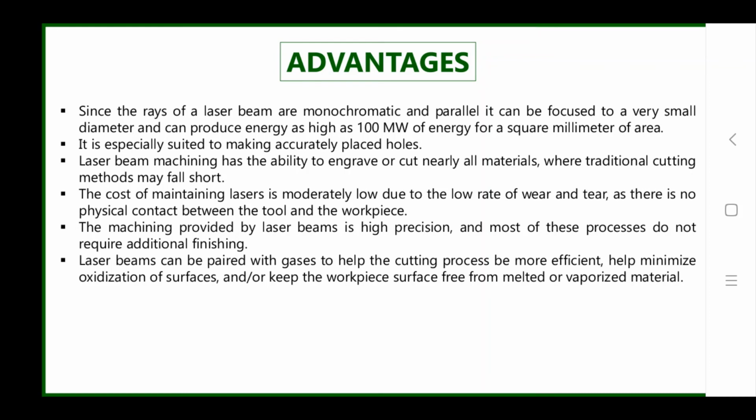The cost of maintaining lasers is relatively low due to the low rate of wear and tear. The machining provided by the laser beam is highly precise, and most of these processes do not require additional finishing. The laser beam can be paired with gases to help the cutting process be more efficient. It also helps to minimize oxidation of the surface or to keep the workpiece surface free from melted or vaporized materials. These are the advantages.